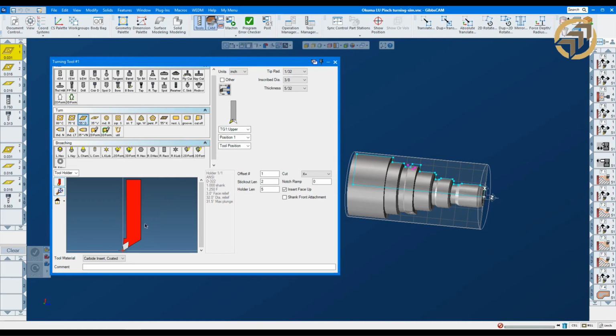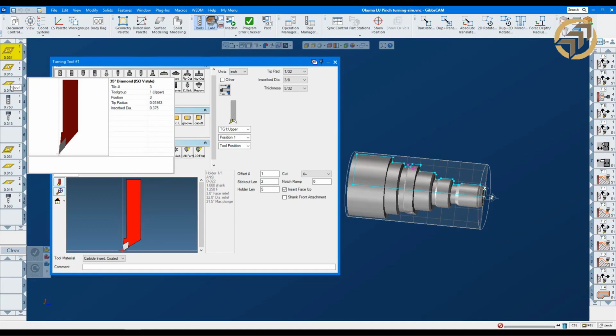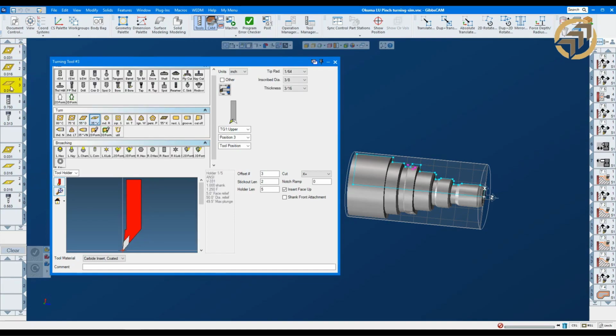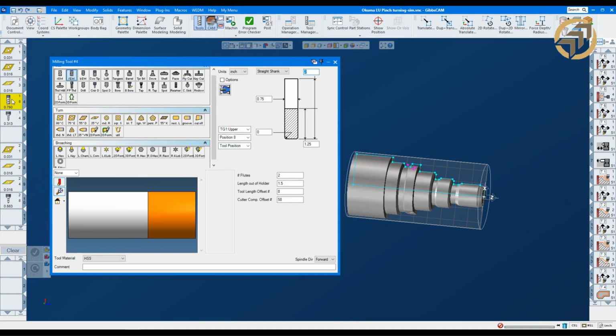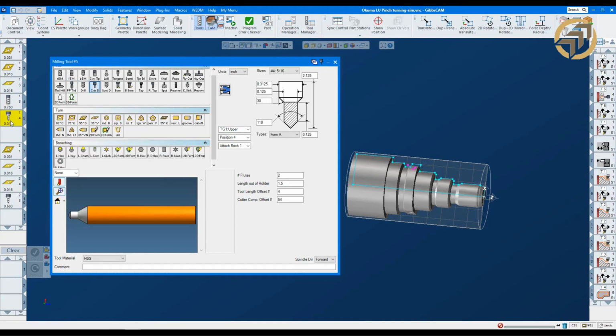So here we are looking at a turning tool, a 55-degree insert. Further down, we have a couple of other ones. It's a 35-degree. So this is basically what we tell the system and select our tools. We have some mills. So this is doing some milling at some point on the part. And then maybe do the center drill. This is the center drill that we basically use to drill the front hole for our tailstock to support the part. So basically we give it the different sizes of inserts, drills, and so on.